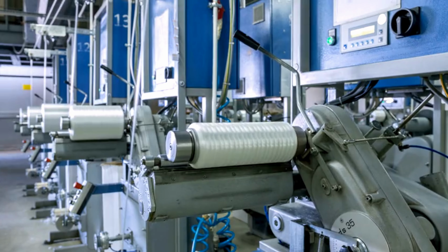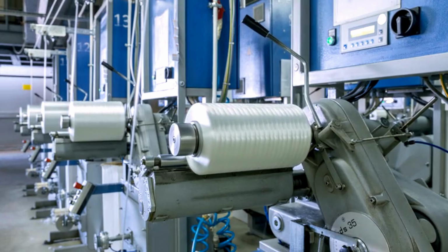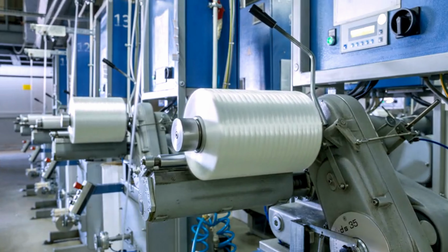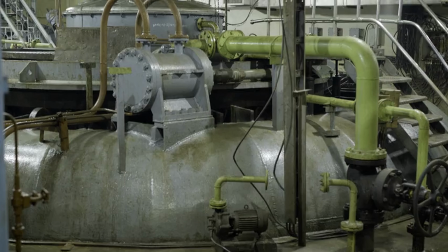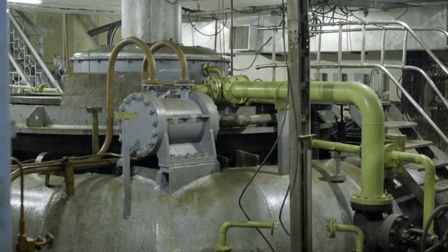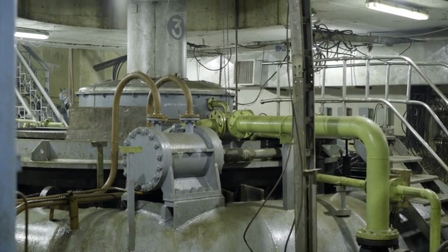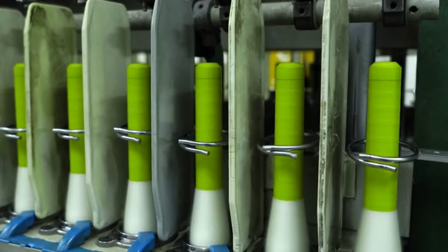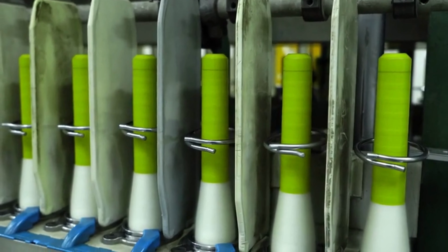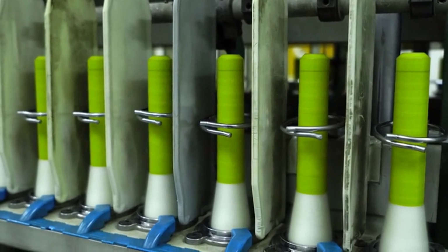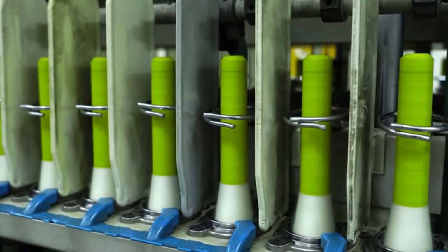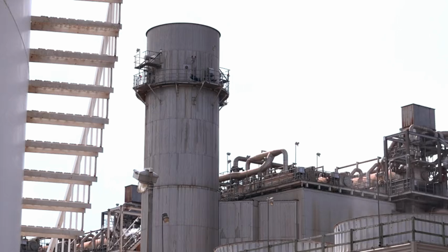2. Next-generation pulping technologies. Pulping has seen significant innovation to improve fiber yield, energy efficiency, and environmental impact. A. Advanced chemical pulping. Modified kraft process uses oxygen delignification to remove lignin more efficiently, reducing chemical use. Closed-loop recovery: chemicals are captured, purified, and reused, common in modern mills. Black liquor recovery: the byproduct of kraft pulping, black liquor, is burned in recovery boilers to generate energy.